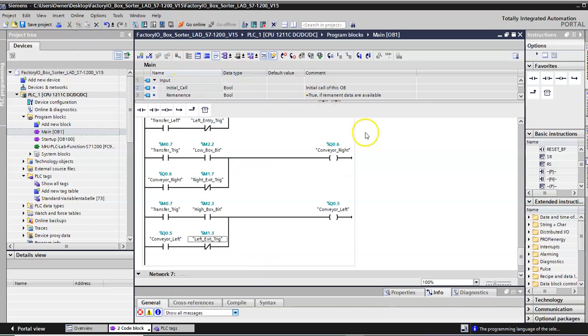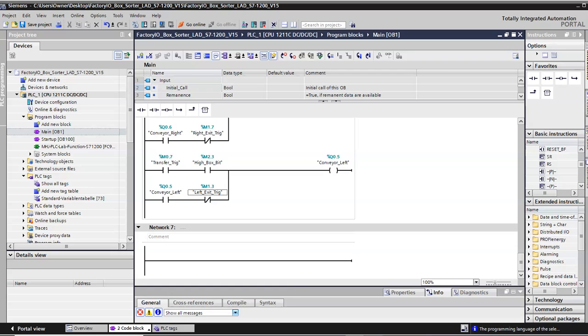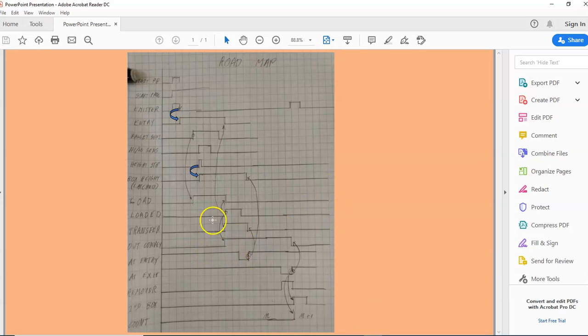Okay, so I think we are almost done. Let's take a look here again. So here's where we're at right now with this left exit. So this turns this off, is where we've gotten to. Now this thing also has to form our second box and count how many boxes we've processed. Now here for the remover, we don't really need the edge trigger signal. We need this at exit signal. What we're going to do is just flip it.